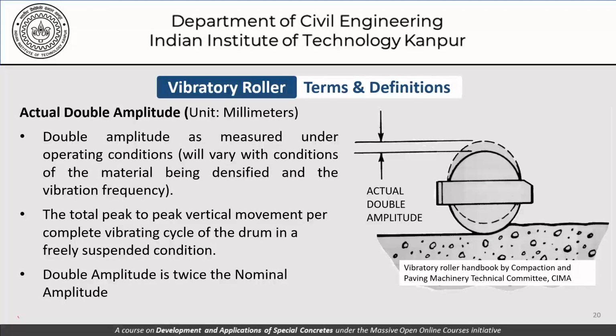This picture shows a schematic representation of the roller. You can see here that this roller wheel actually oscillates between these two positions, here and the bottom is shown here. And as it moves in one pass, it is trying to compress or cause settlement in the layers ahead. So if this process is repeated several times, we will have this concrete getting compacted.